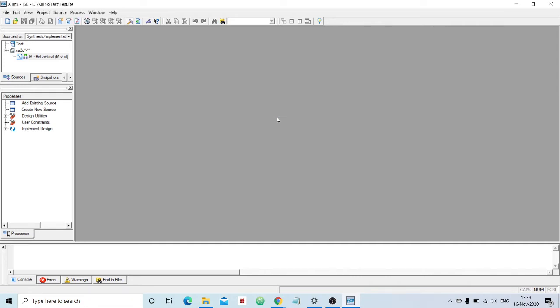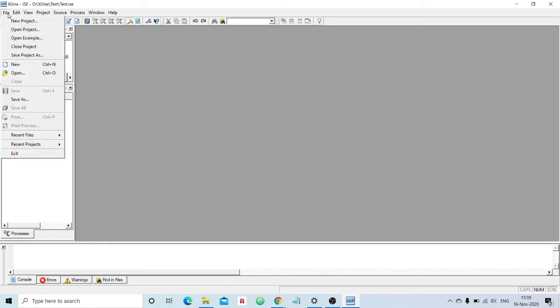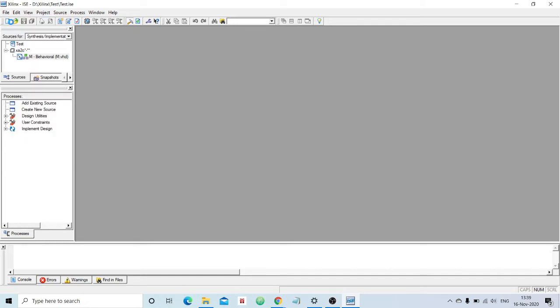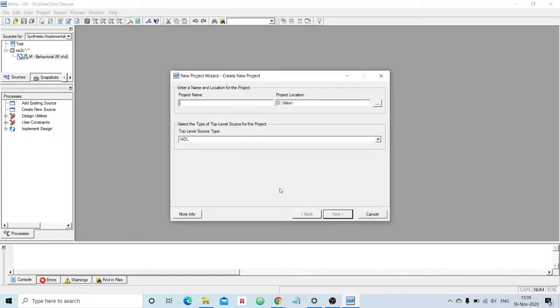Clear? Okay. Remember, every experiment in part B has to be carried out by defining a new project. So to define a new project, click on the File menu option, then choose New Project, and a window will appear. Okay, and give a name for the project. Let us state our requirement is to simulate the working of a 2 input bit AND gate. So I will give the name of the project as AND gate.